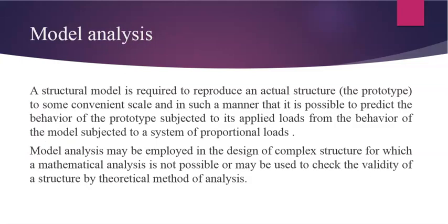The next topic is model analysis. A structural model is required to reproduce an actual structure, which is a prototype, to some convenient scale and in such a manner that it is possible to predict the behavior of the prototype subjected to its applied loads from the behavior of the model subjected to a system of proportional loads. Model analysis may be employed in the design of complex structures for which mathematical analysis is not possible, or may be used to check the validity of a structure by the theoretical method of analysis.